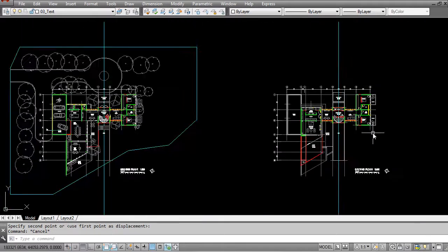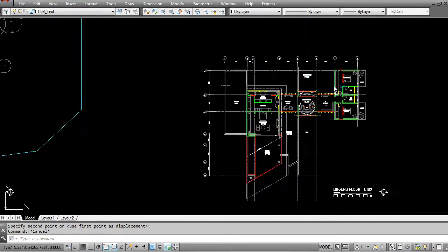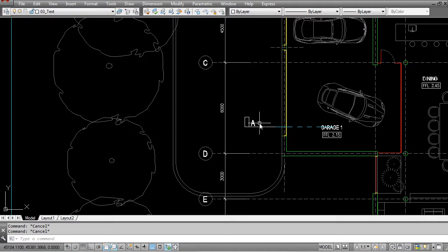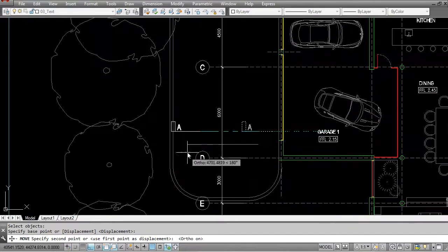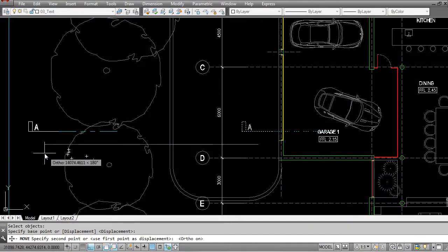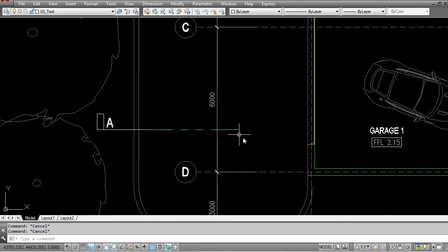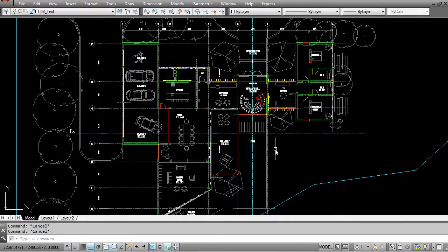We'll also be cutting through the bedroom upstairs, so we'll be able to see a part of the bed if we do draw all the furniture in the sections themselves, and we'll be able to understand what's happening as we make that cut, especially with all of these slabs. So all you need to do here is move your section line out so that you can see it quite clearly. So you can either move it right out of your drawing, or you can leave it roughly about here. I reckon I'll leave it more or less in that location. And then move your section line till about there.